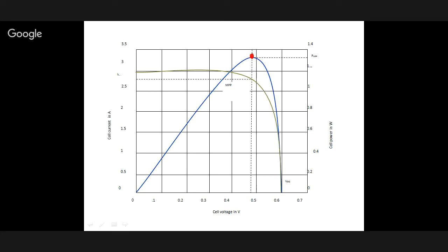आपका maximum power point ये है. So इस point को reach करने के लिए you have different methods. One of the methods which I told you was perturb and observe. Voltage and current को ले लो, or you write the algorithm and you find out the duty cycle at which you have to fire so that impedance matching occurs. So for example, in this case इस point में आपको एक voltage and current मिला.